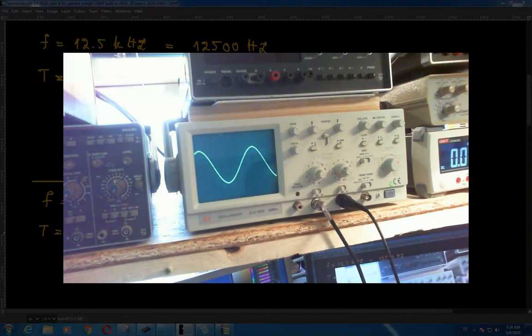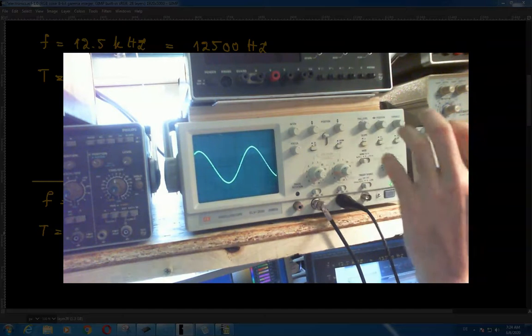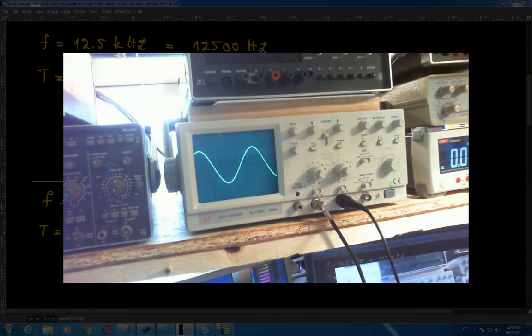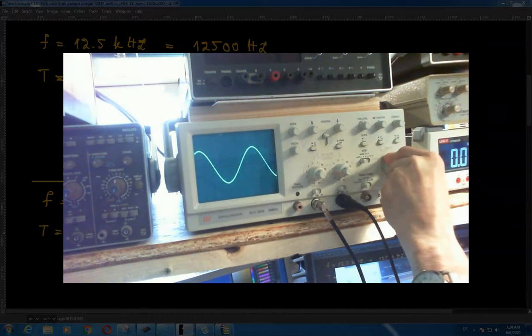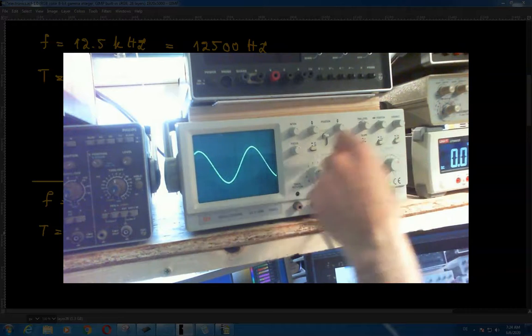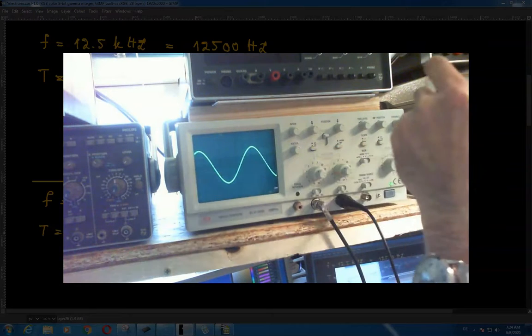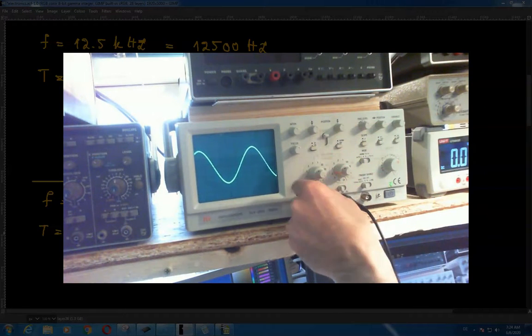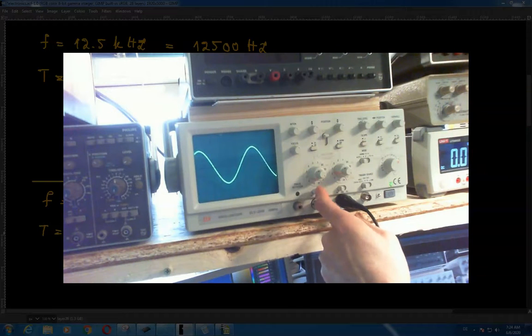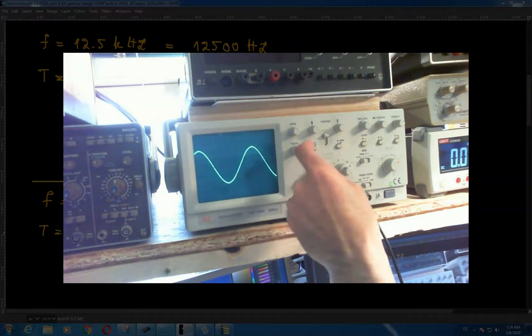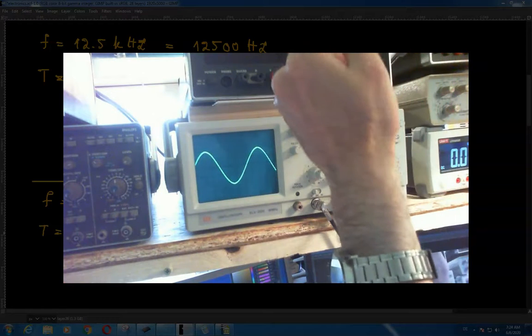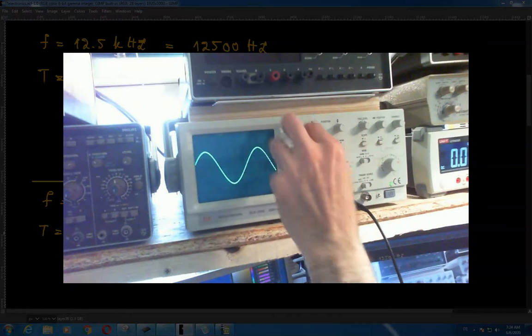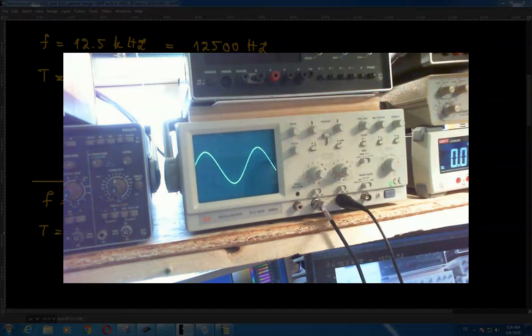In every oscilloscope these are a little bit different, but essentially the main things that you need to understand from the oscilloscope is the time per division, which is this knob over here, the time base, this is the volts per division, this is the time base, and this switch over here that lets you look at AC or DC, and basically this position over here and this position over here, right? And then there is the intensity and focus, you know what they are.